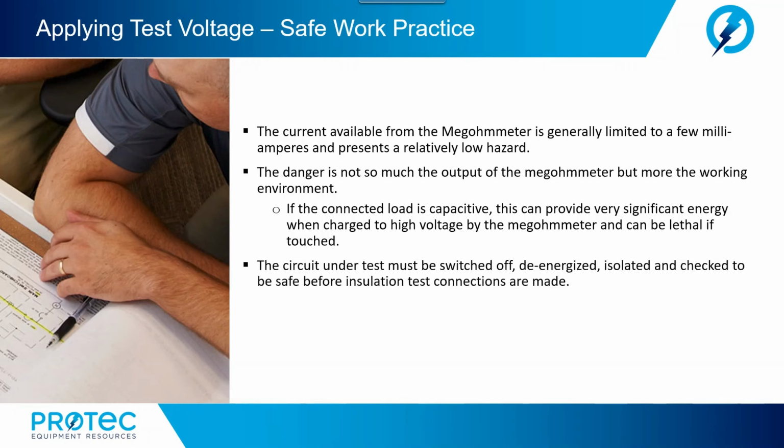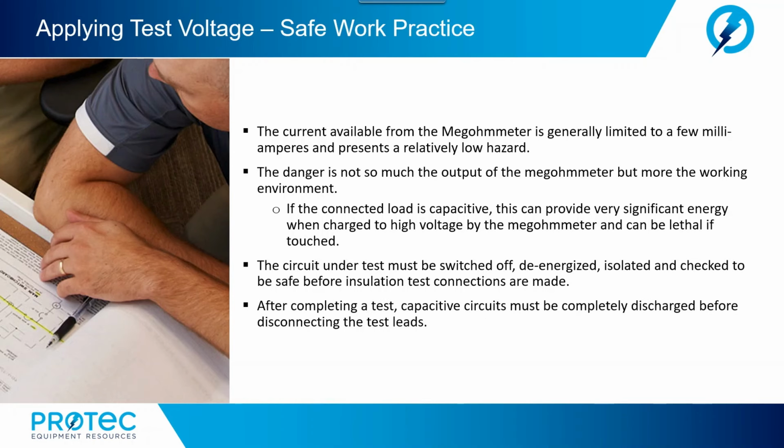The circuit under test must be switched off, de-energized, isolated, and checked to be safe before insulation test connections are made. Test before touch every time without exception. After completing a test, capacitive currents must be completely discharged before disconnecting the test leads or handling the circuit.